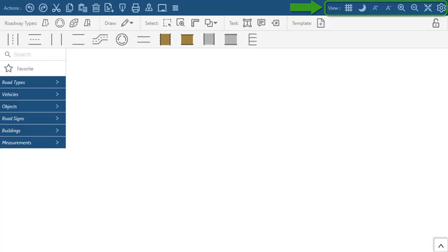The actions on the right side of the action bar pertain to the properties of the canvas. Use the grid icon to toggle the measurement grid. This grid can make it easier to align items on your crash diagram. Use the moon icon to toggle night mode. Turning on night mode darkens your screen so that your vision is not impaired by the light of the computer screen in darkened surroundings.